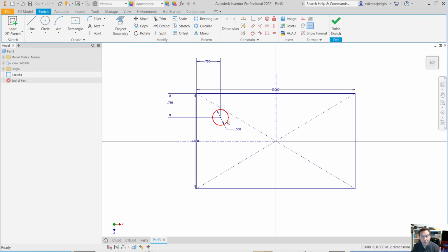So here's how to mirror. Click on what you want to mirror. And by the way, I hit Escape a moment ago, so you might want to do that before you do this. Select what you want to mirror. Now, you could go to the mirror tool right up here. And look at that, it's set for a mirror line. Just go ahead and click here. Oops, you know what, I should have clicked on that first. There. Let's restart. Done. Okay, go to mirror.